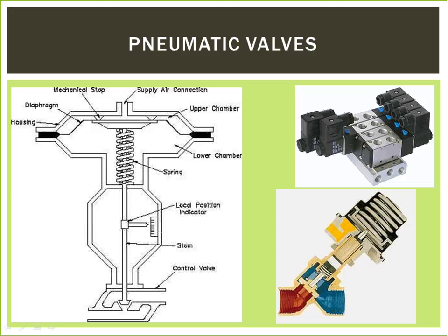This type of pneumatic valve classification refers to the manner in which airflow direction is switched. For example, in a two-way directional valve, the valve is either open, airflow is enabled, or closed, airflow is prevented. In order for each port to assume an open or closed position, an actuator moves a valve spool into position.